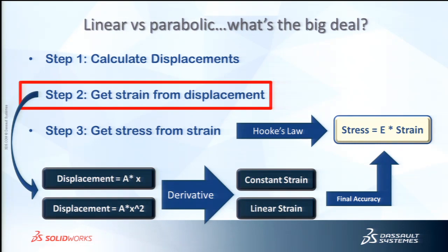So this is what's really going on behind the scenes. That very first equation I showed you, F equals KD: all we can measure is the D, the displacement. It calculates the displacement, takes the measurement. From that, because we know how stress and strain are related, we can calculate the strain from the displacement because of Poisson's ratio. And then we can calculate our stress from the strain.